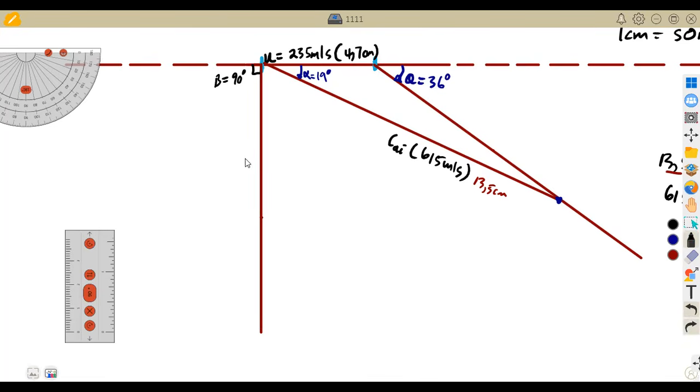All right. So since we have taken this point when we joined to this point here, it means we can also measure the inlet, that we have the relative inlet velocity. So here we can measure our inlet velocity. Place your ruler to this point. So if you're to measure, you're going to obtain 9,3 centimeters.